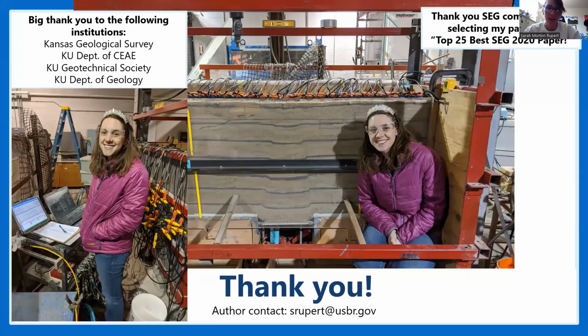We did work only in a dry environment because it was easier, first of all. But theoretically, if it's saturated, there should be probably some more cohesion, so I think you would still probably be able to see changes. You probably wouldn't know from the surface wave data that it's saturated, because it's shear wave velocity, and shear wave velocity cannot provide you information about water saturation because water is not rigid. It has no shear modulus. So I'm not sure that answers your question, but let us know in the chat box. But there's another one on here too.